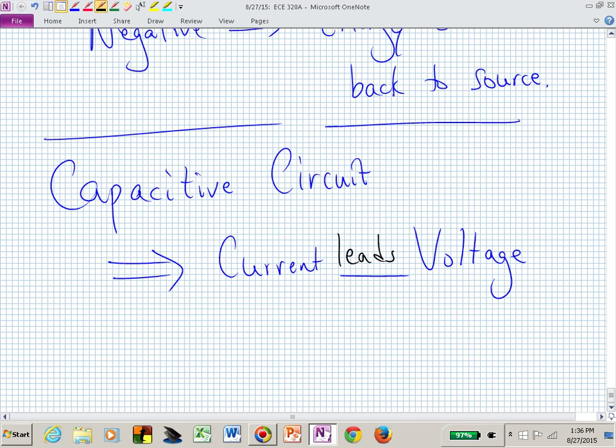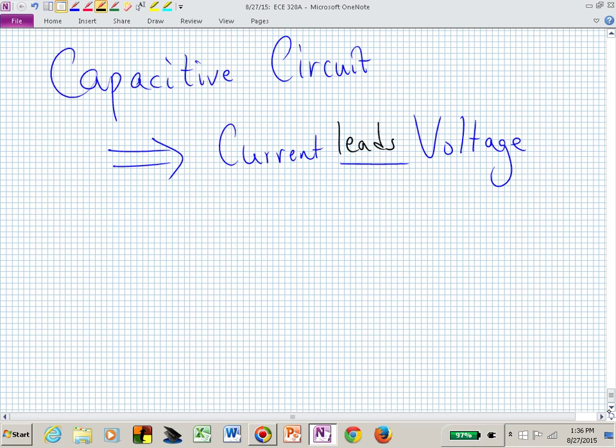We want to now be playing with these Qs to make them smaller. Ideally, we want a power factor of 1. We want to see purely resistive loads. It's probably not going to happen. But the power company is going to charge you if your power factor is too low. They're going to say, you are really hurting me because I'm really having to crank things up voltage-wise in order to sustain the current demand that you're asking me to deliver. So let me get off my soapbox.